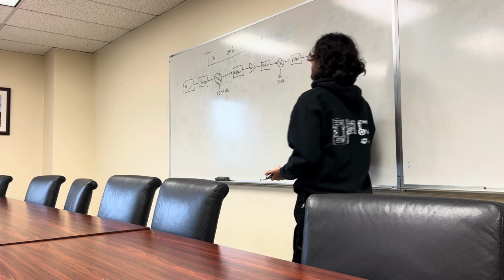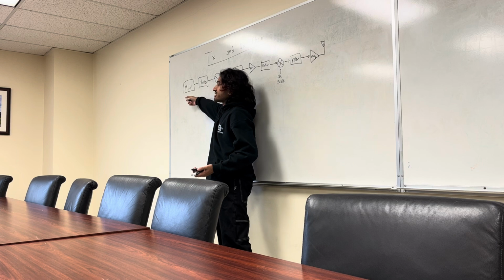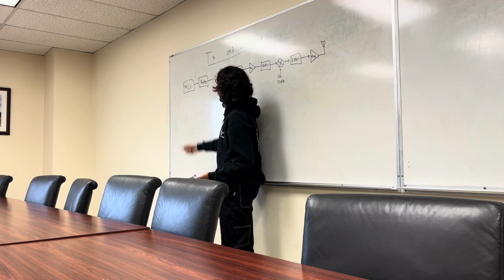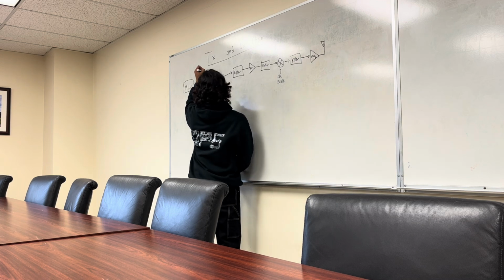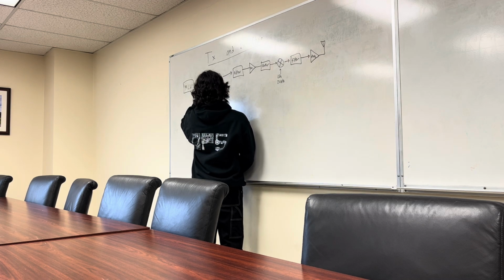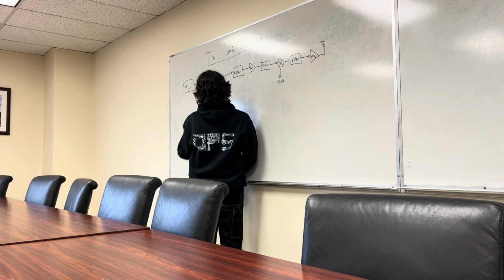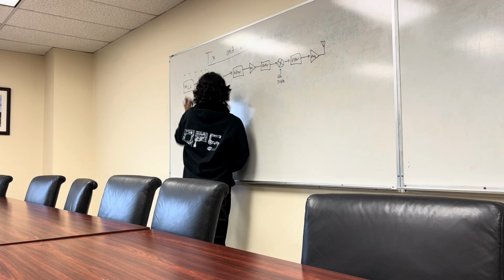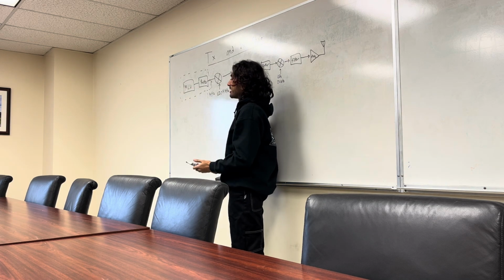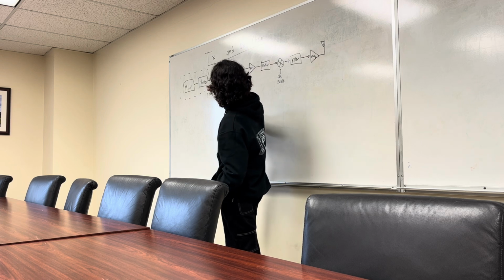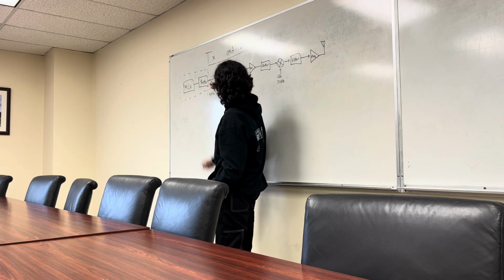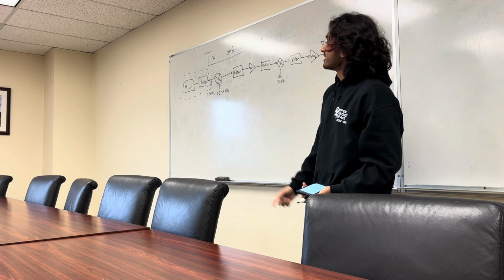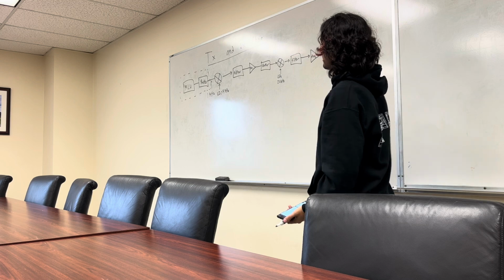But one thing we've not simulated or worked with so far is this MCU. So this is a new aspect of how you model this, right? Before, we just said, okay, we have a 1 megahertz signal here, but we didn't really consider what all this looks like. At the end of the day, we know we need a buffer to make sure our MCU is not loaded. And we need to make sure that we have a strong enough signal here, right? So that's one important thing we look at in this next module.